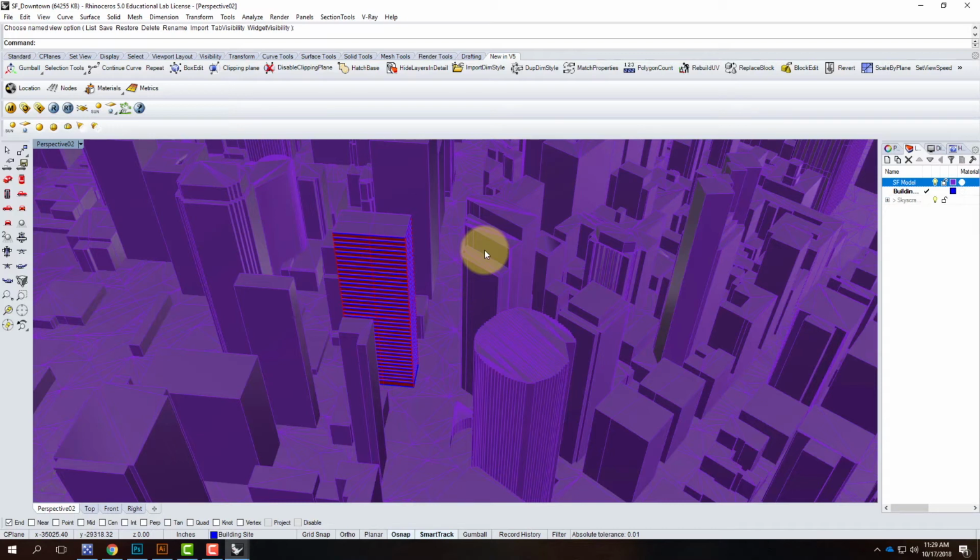The purpose of a V-Ray proxy object is for geometry that is very repetitive or really big and difficult to work with, i.e. the city of San Francisco. You can make it an object that only V-Ray sees, and when you do the rendering, that object shows up. When you work in Rhino, that object isn't there anymore. So it's essentially like keeping the city of San Francisco without actually having to keep the city of San Francisco in your file. So it can be really useful in some contexts. For right now, we're going to skip over it. I'll come back to that a little bit later on.